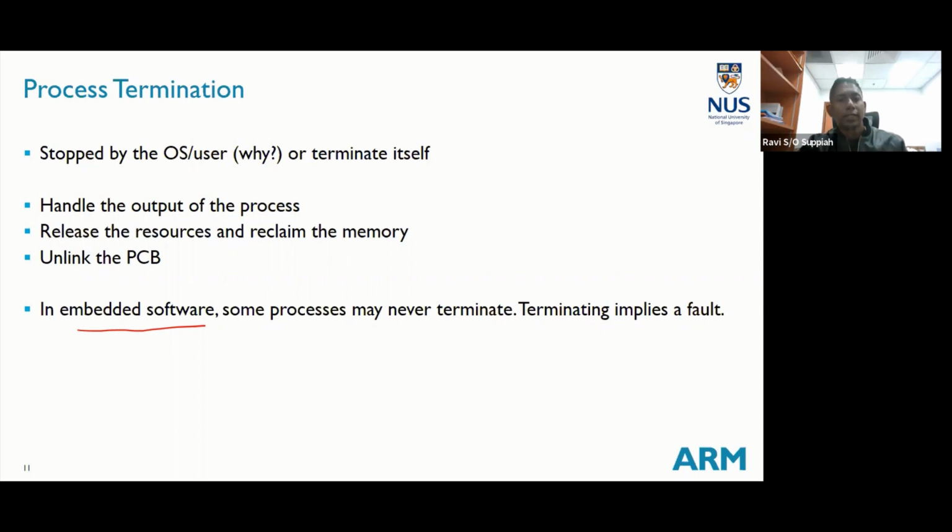If the task terminates, then it could be that something really went wrong, correct? In embedded OS concept, though it is possible to terminate a task, if you intend to do something only once, you will not create a task for it. You can just write it as a normal function call, a module or something, and just call it.